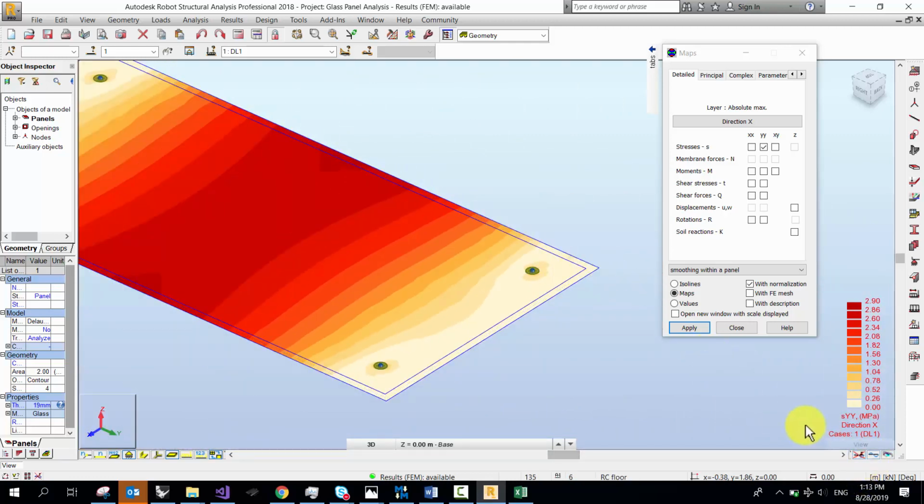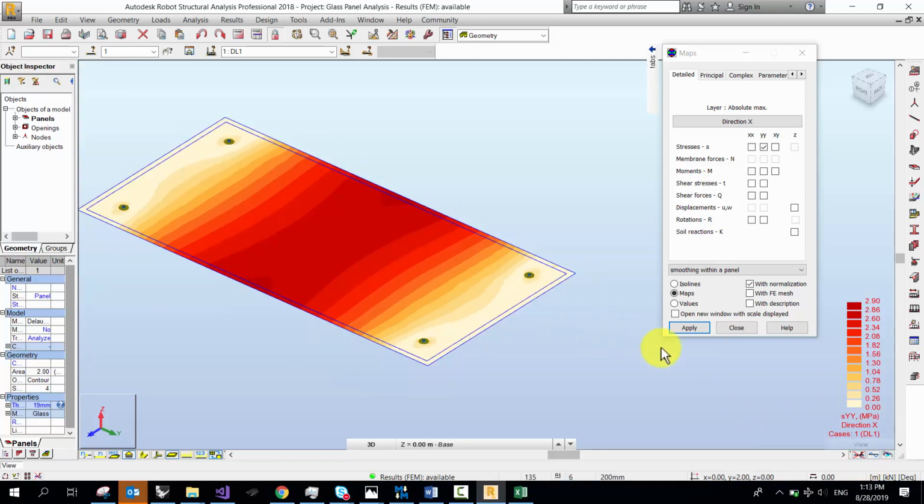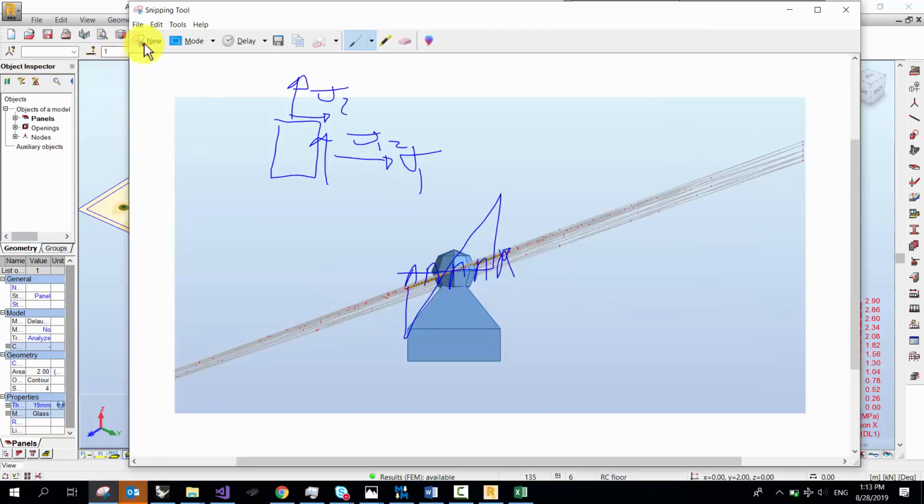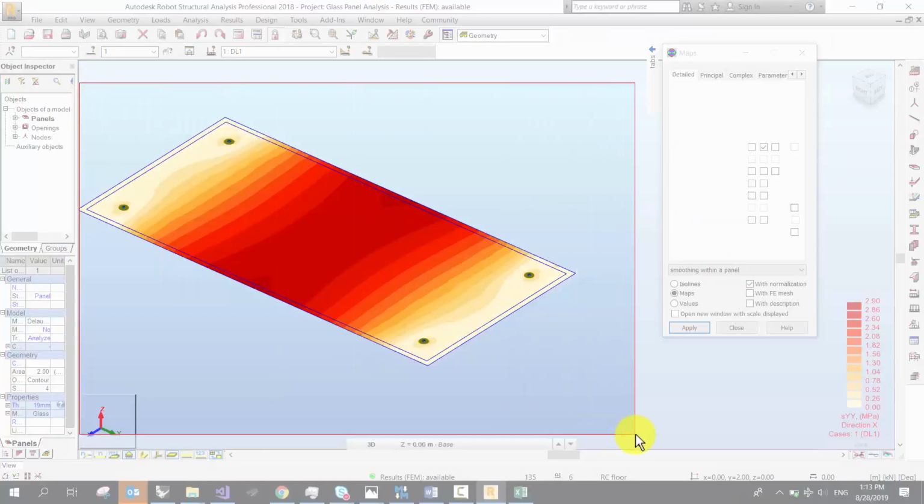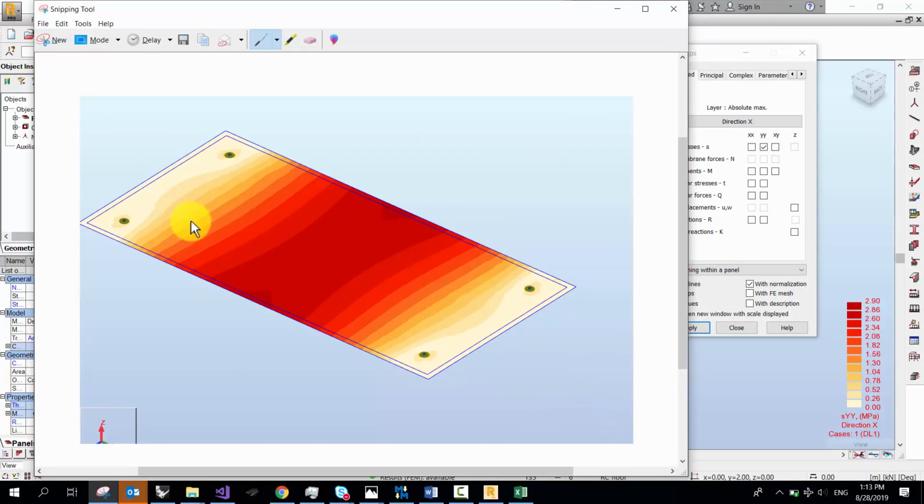This will be either two. We keep it that way, so only two up there too. Just like actually pinned. The other two will be more releasing, flexible. I completely agree with that too, because obviously we're doing this quickly. If we want to make sure, the boundary conditions in a finite element model, just so you know, are the biggest danger, because you're actually throwing in there something that's infinitely rigid, and nothing in the world is infinite, right?